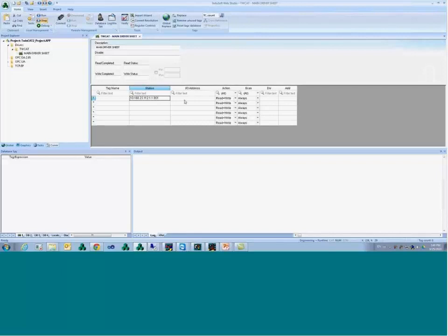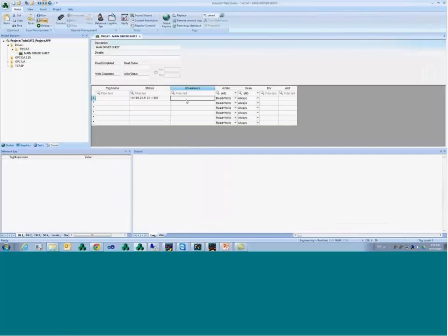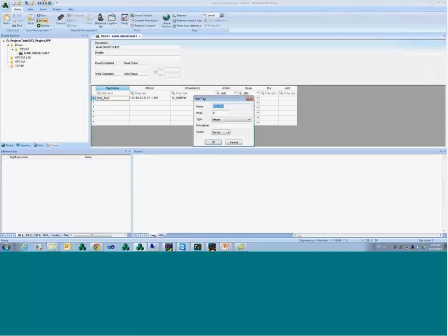Okay. All right. Which variables am I going to talk to? I look here on TwinCAT, and I have a variable called D_DINT_test. Since that's a global variable, it starts with a dot. So I'm going to put here, as my Web Studio tag, let's say, INTTest.